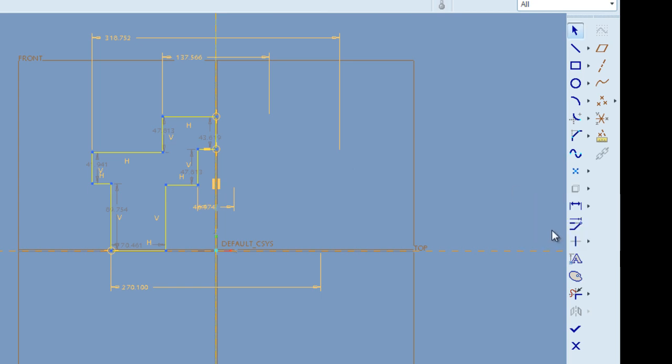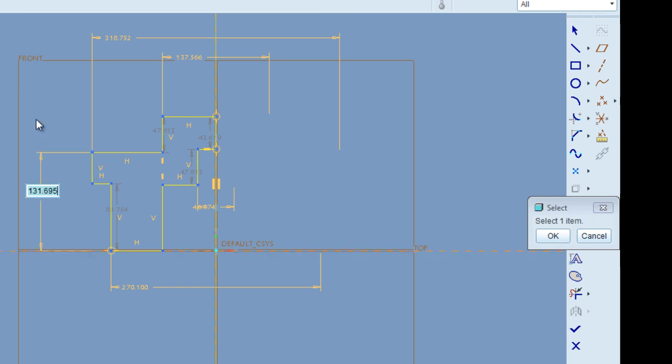Now we do want to set a coincident constraint between this line here and this line here. The reason is that this surface defines the top of the part, and this surface is where the peg, the stud, will insert into. Then we'll just go about defining a few more dimensions. These are just regular dimensions, so these aren't revolved, so they're not really radial. They just define what the height is. So we'll define a few more of these dimensions.